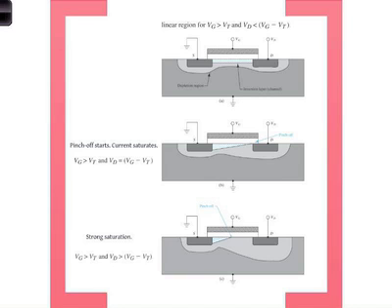Okay? Now, how does that happen? Because the electrons from far away can get attracted here. So locally, you can get a very high concentration of electrons. Of course, even in a p-type material, you have plenty of electrons. Well, the only thing is that you have a lot more holes than electrons. So if you apply a positive voltage, you start pulling the electrons closer to the interface. So locally to the interface, you make the material n-type. So you convert the p-type to n-type. Okay? And that's called inversion. Locally, just near the interface. Okay? And that's this light blue region. It's called an inversion layer.